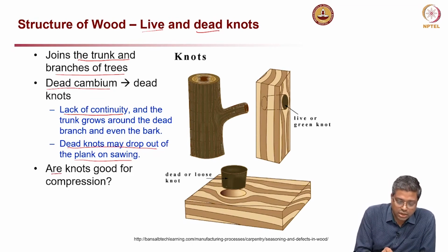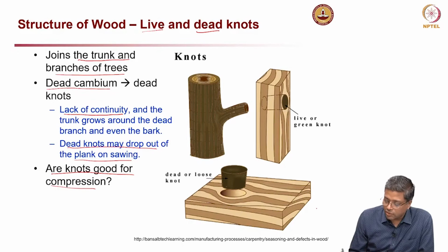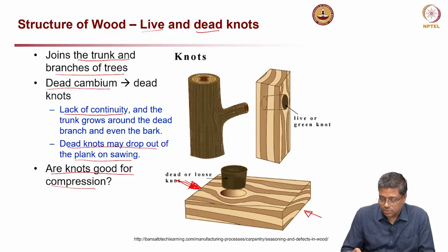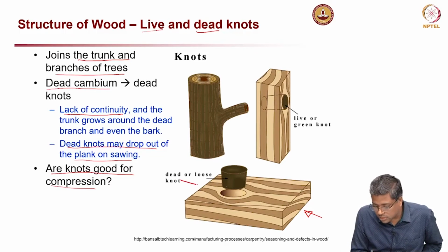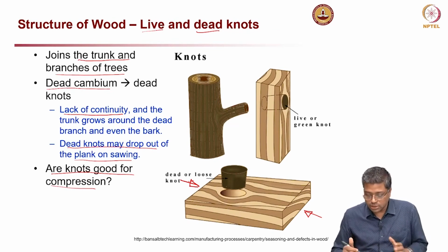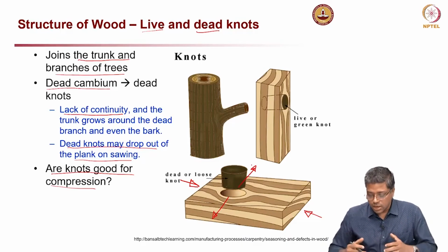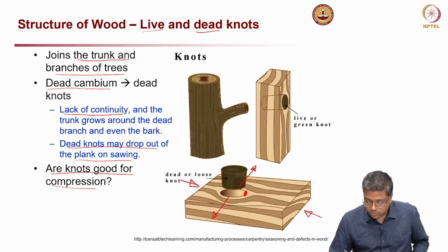So, the question here is, are knots good for compression? Look at this picture here. If I compress the wood in the direction parallel to the grains, there will be a lateral stress generated here, and stress concentration will happen here.